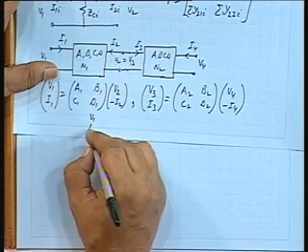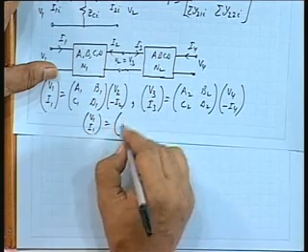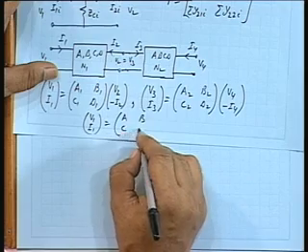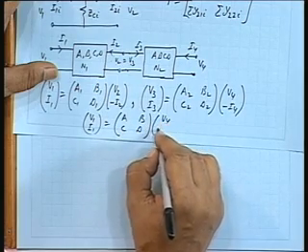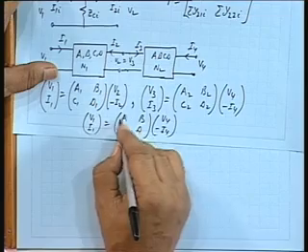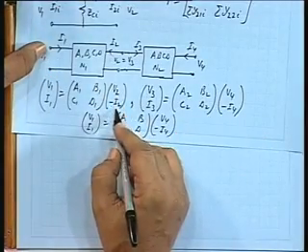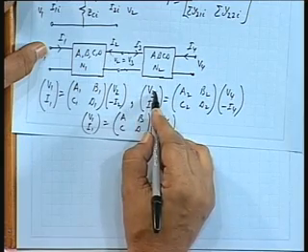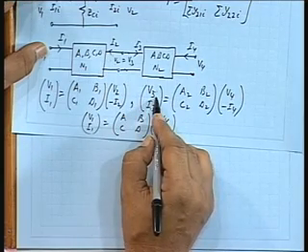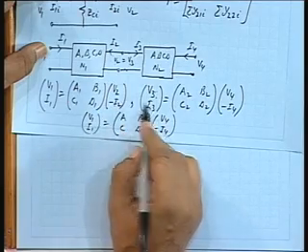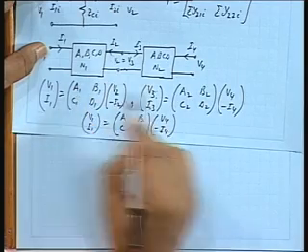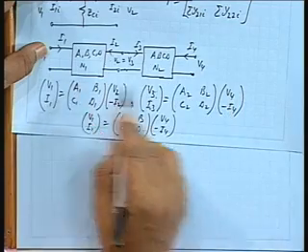So, I want V1, I1 in terms of A, B, C, D, V4, minus I4. Is it the product of these two matrices? You have to establish that. You can see V2, minus I2 is same as V3, I3, because minus I2 is I3, so you can replace it. So ABCD matrices will be just multiplied.